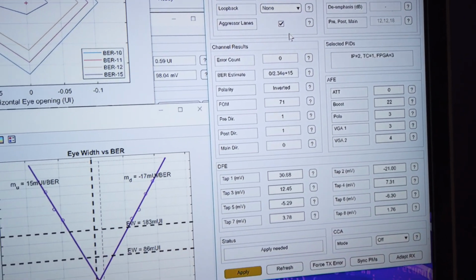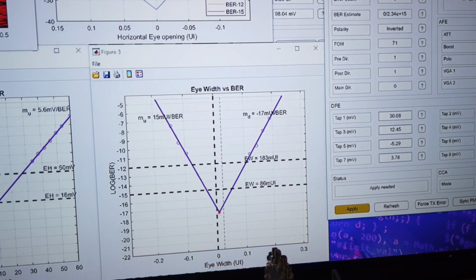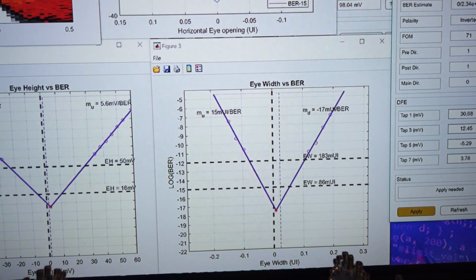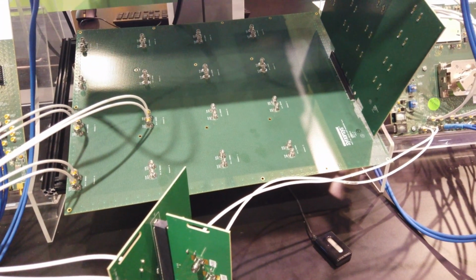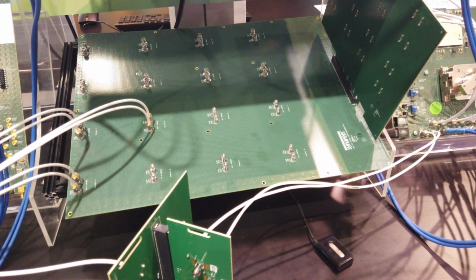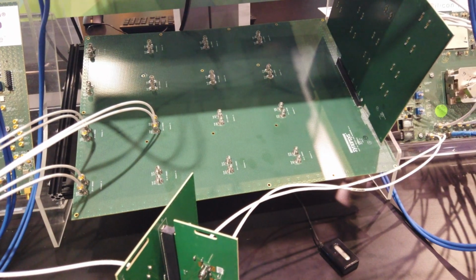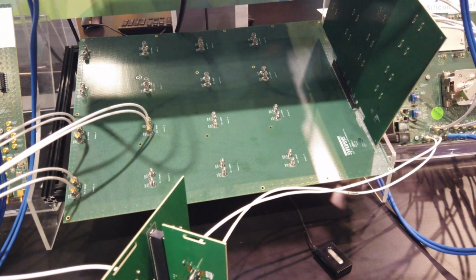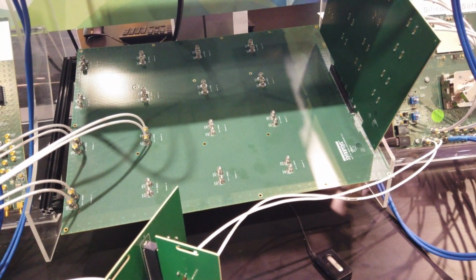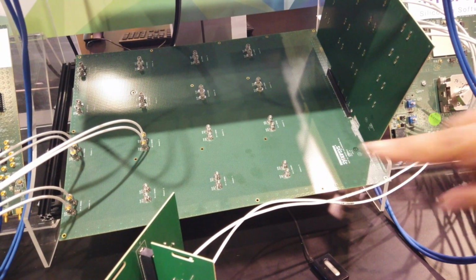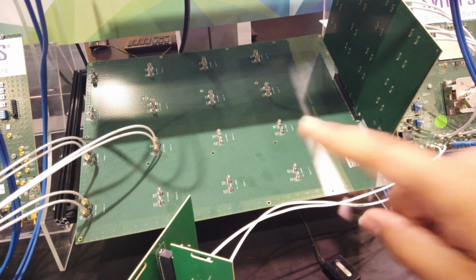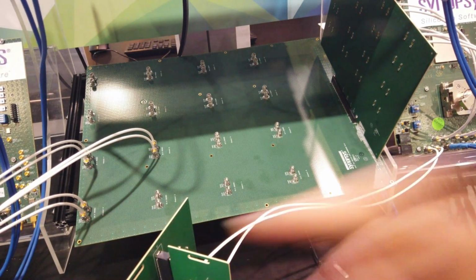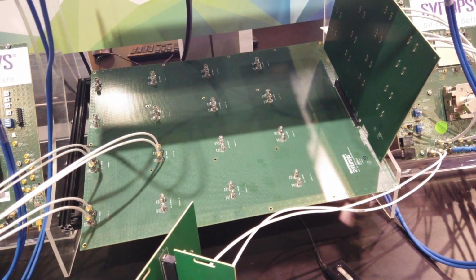On the bottom shelf, we're also demonstrating a channel that is created. It's an ISI board that is built by Synopsys. Again, this board has different traces, and what we are demonstrating right now across multiple channels, we are running 36 dB insertion loss just across the PC board material, ISI board, going from one PHY card to another PHY card.